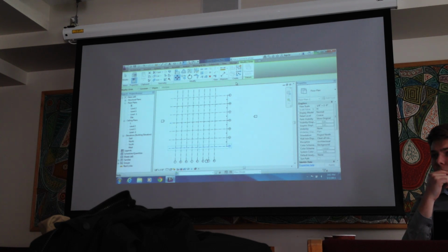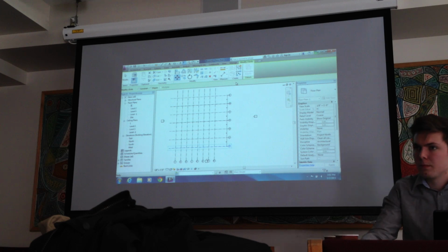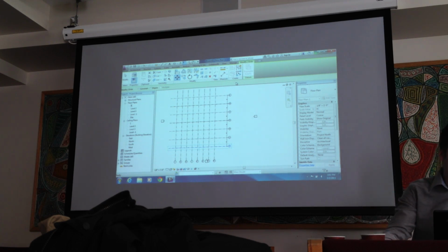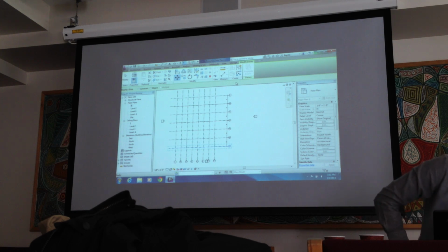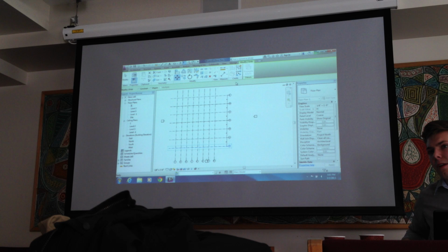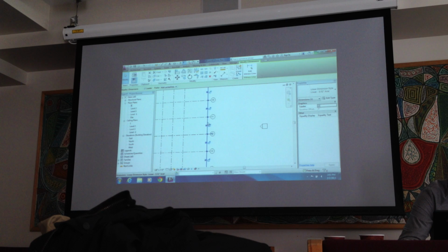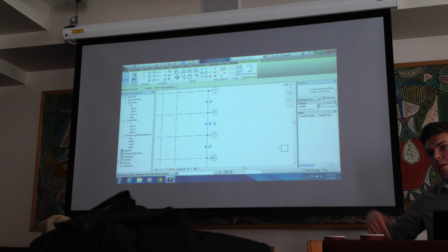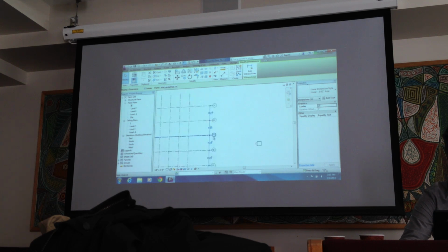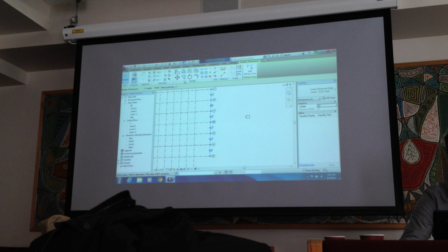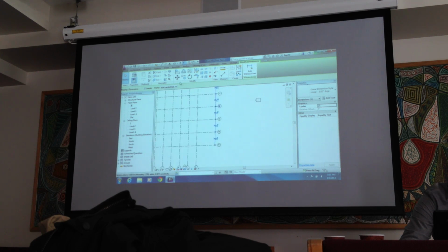So did you manage to get it working? I don't see the lock thing. You don't really need to worry about it right now. It's more useful for walls and roofing and items like that. The best way I could describe it is if you wanted to lock, let's say this one, you don't want this one to expand or contract when you're moving dimensions. So this one little grid line here is locked, so these two won't move. As all the other ones are unlocked, if you decided to move the grid line down, it will change them all other than the ones that you locked.